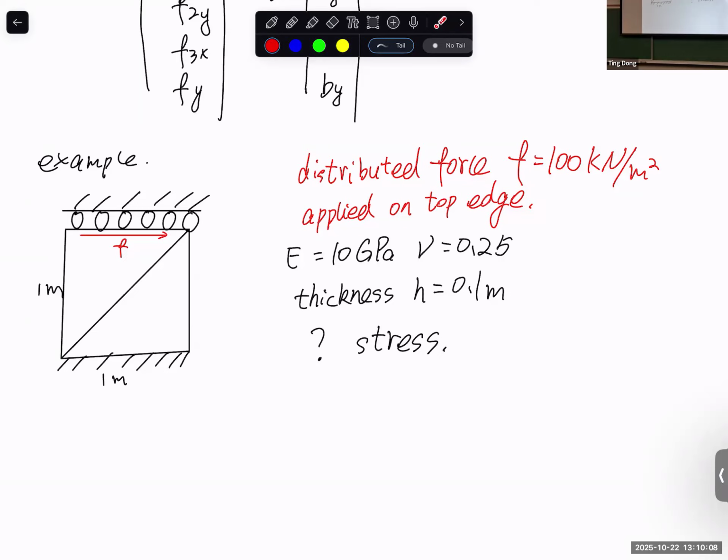Well, let's first ask how many unknown degrees of freedom are in our structure? How many? 2. Any other opinion? 1. Who said 2? Which 2? The top 2 nodes. Why 1? Basically, due to the roller, it's only capable of motion in one direction, thus only has 1 degree of freedom.